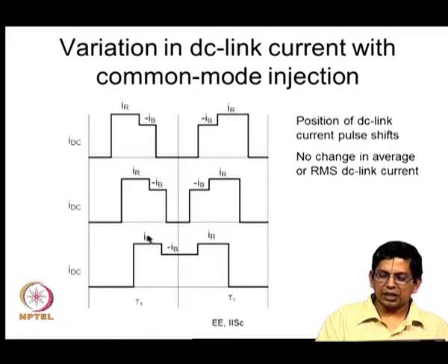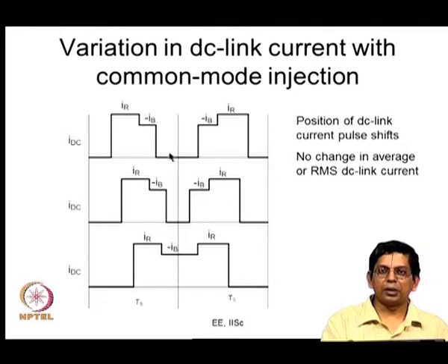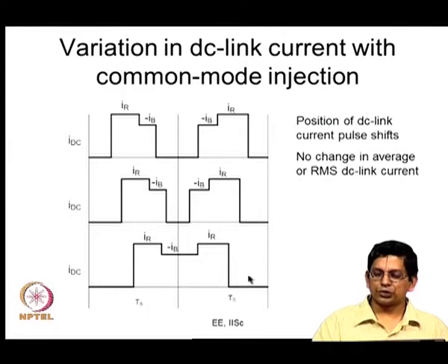So, here again this is IR square, IB square. If you try to evaluate this RMS value, you will get IR square into T1 plus IB square into T2, the whole divided by Ts. So, the whole thing under square root would be your RMS value. So, this RMS thing also does not change. This is true about this subcycle, this is true about every subcycle which is yet to come and every subcycle which has been crossed.